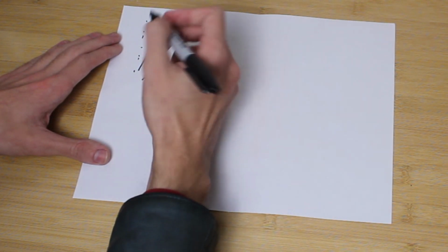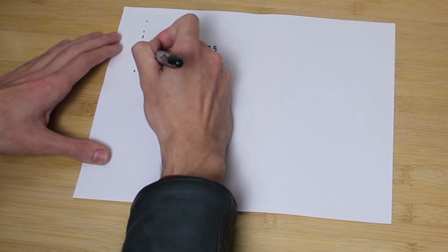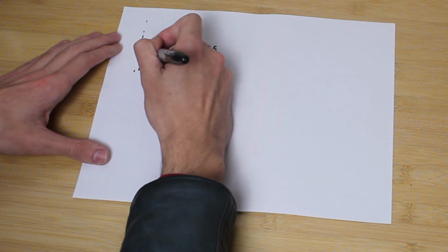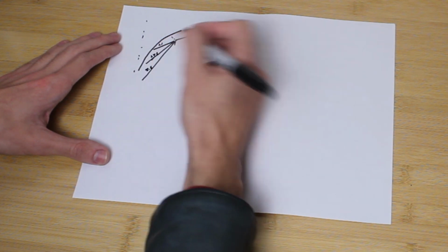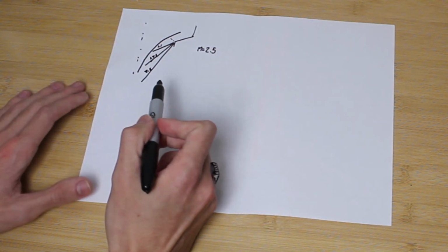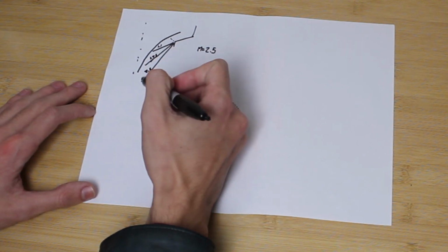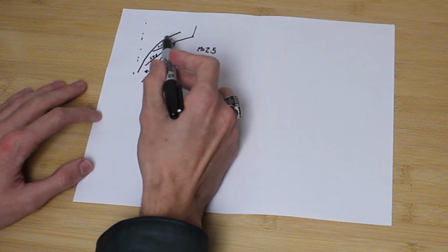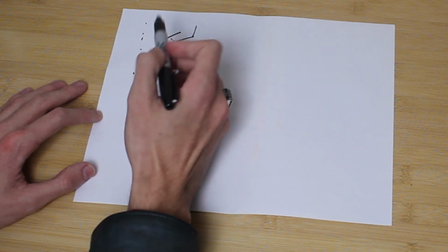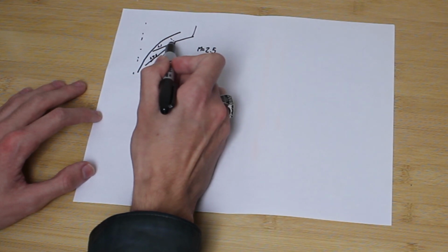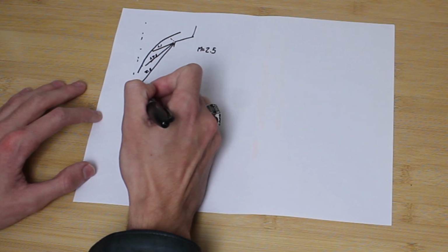So then we can just go ahead and say that this is the Mach equals 1.1 line, this is the Mach equals 1.75 line, and then this is the Mach equals 2.5 line. And so what that means is that by solving this setup we've got here, we will have three positions on the surface of our spike, because we'll be able to solve for the length and the position of this point here, this point here, and this point here.